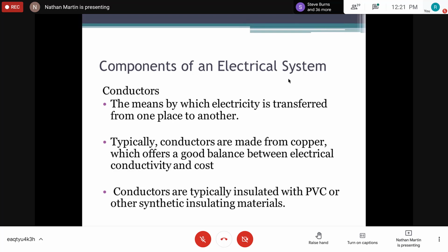The typical temperature range, when we're talking about conductors or cables, we talk about 60 degrees, 75 degrees, and 90 degrees in terms of their temperature range, right? Now, operation of any cable above its stated temperature range will cause that cable to degrade faster than necessary, right?